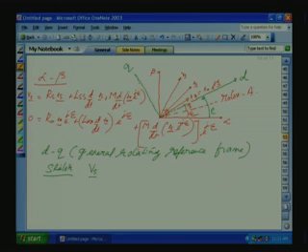Vs, originally defined with the stator axis, we have to move to the dq axis. Now the angle, this is the general rotation. Anti-clockwise rotation is the general rotation of all the axes. So when we go here, the angle we have to reduce it.